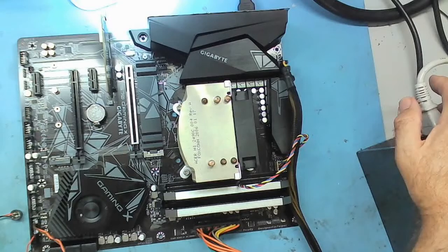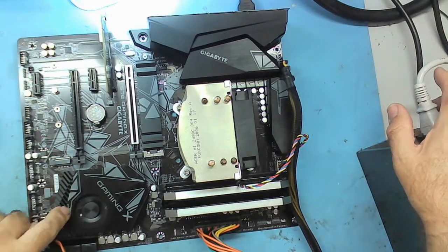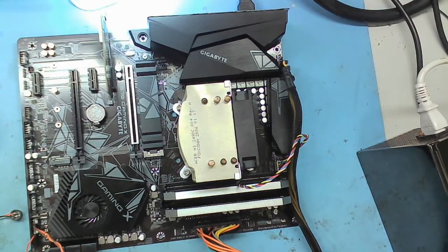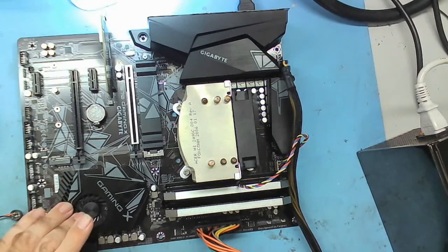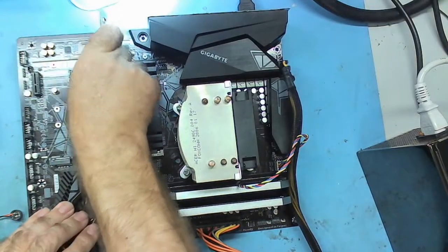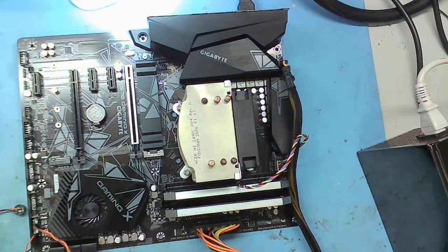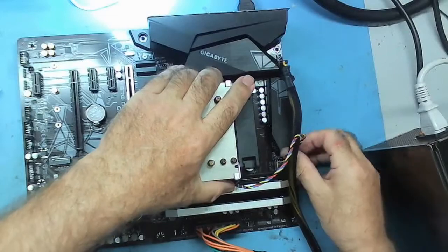But what we can do is check the voltages, because I know the Northbridge chip will be the same, because it's the same chipset as the other one. So let's have a look and see what we got here compared to that first one. Because for sure this one powers up. Okay, probably need to take the heat sink off to get at it.